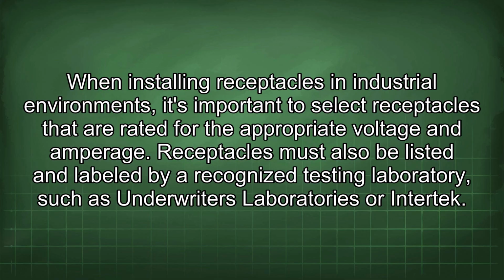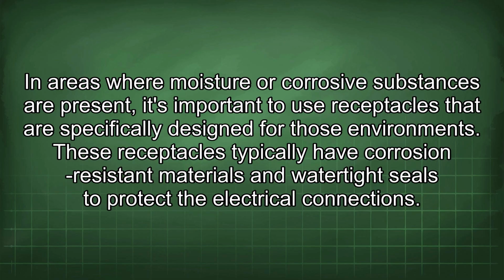Receptacles must also be listed and labeled by a recognized testing laboratory, such as Underwriters Laboratories or Intertek. In areas where moisture or corrosive substances are present, it's important to use receptacles that are specifically designed for those environments. These receptacles typically have corrosion-resistant materials and watertight seals to protect the electrical connections.